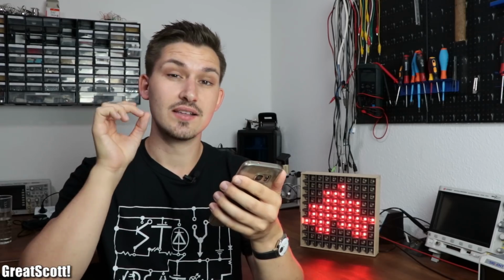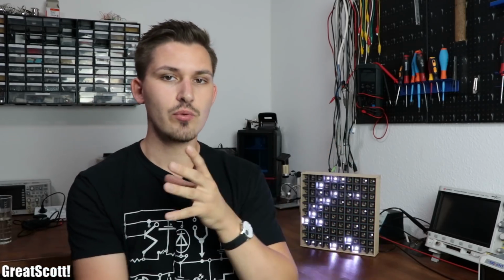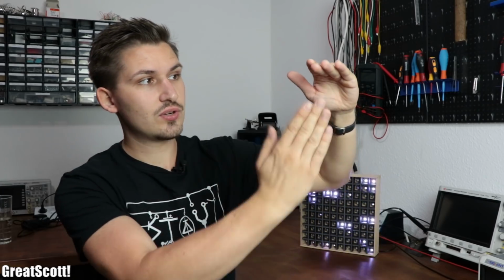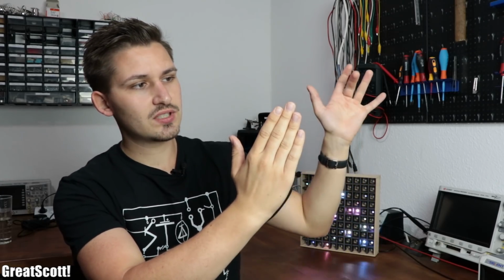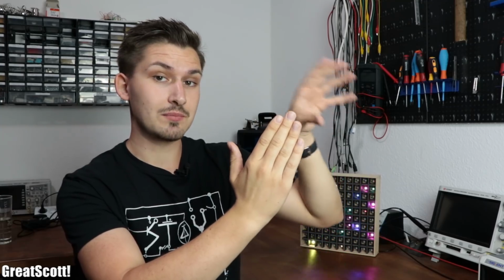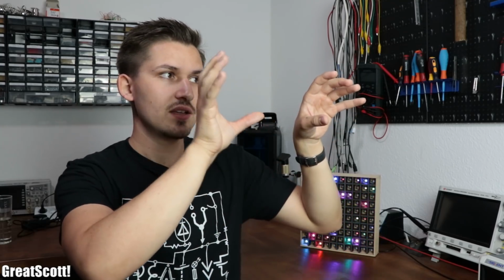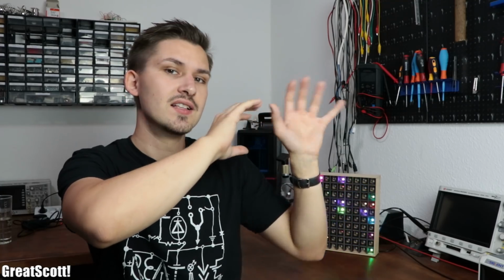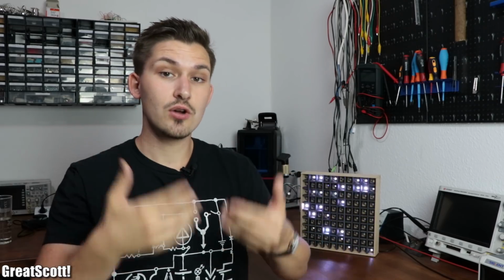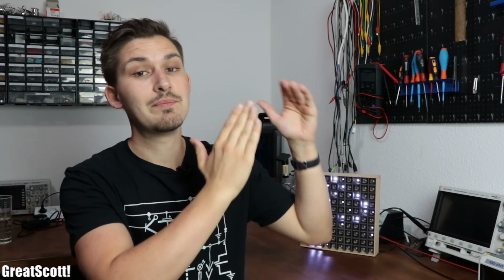So you have 2S batteries, that's 7.4 volts. And then you said the XL6009 can do 3 amps. I looked it up before. It's actually 4 amps, but that's the switching current, 4 amps. So as you might know, with a boost converter, you got your coil and you got your switch. And the switch is then used so that current flows through the coil so it can build up its magnetic field. And then the switch is opened so that the energy of the magnetic field can be pushed into the output, so the voltage rises. So it's important to know that the 4 amps is the switching current that can be on the input.